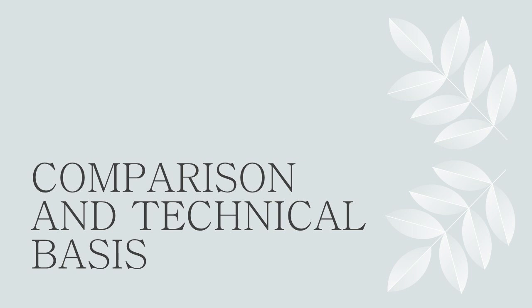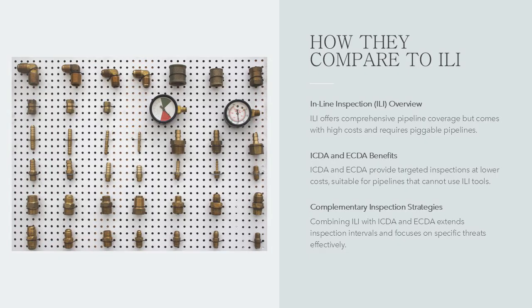How they compare to ILI, technical basis of ICDA and ECDA. Now let's compare these methods to ILI and understand their technical foundation. ICDA and ECDA are credible alternatives because they are based on sound engineering principles and validated through field data. ILI provides full coverage but at a high cost and requires piggable pipelines.